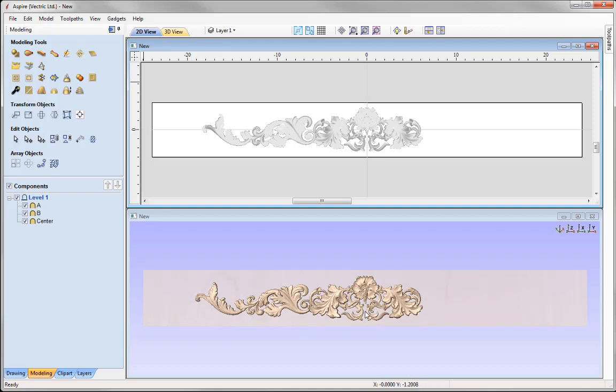So I'd like to cut this out and attach that to the end of our flourish just to finish that off. And that'll be quite nice, having the sort of repeated element of it in the centre of our design as well as at the ends of the design as well. And so to do that, what I'm going to do is draw a vector around the area that I'd like to keep, and I'm going to look at using this option over here, clear area of selected component outside selected vectors, and that's going to essentially remove everything outside the vector that I draw up.